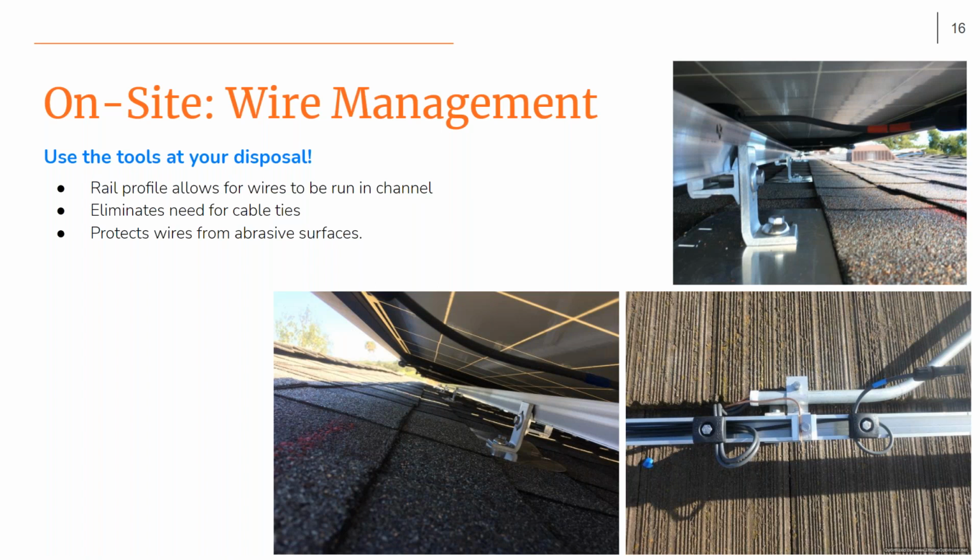Yeah. And I think we were a little remiss here, Andrew. We probably could have called out the newish lineup of conduit mounts. We've now got 3/4 inch and 1 inch PVC and EMT mounts that help any installer do a better job securing conduit on the roof. And they're also flashingless and don't require prying up shingles anymore. This is older technology showing our umbrella ceiling flashing technology, but as you saw with Speed Seal, you're not going to have to pry up and get under those shingles anymore.